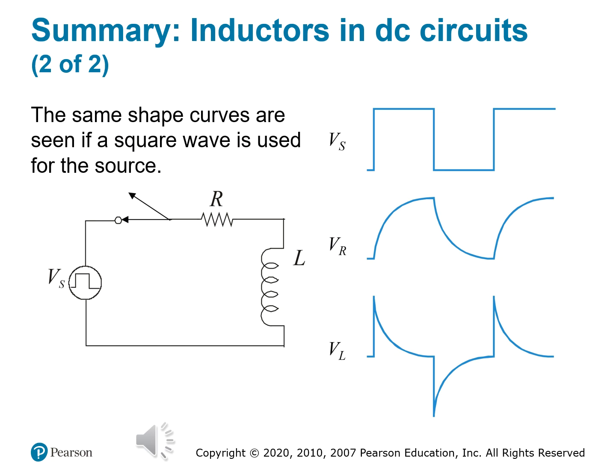If we have a square wave voltage source, V sub S, and that's feeding a series RL circuit, the waveform flips between on and off, basically applying the step voltage over and over and over. This rapid switching is common in pulse width modulation, switch mode power supplies, and digital control systems. And what is the inductor doing? Let's take a look at that voltage in the graphs. V sub R, across the resistor, follows a curved exponential rise and fall. And that's because current through the inductor ramps up and down gradually, even though the voltage flips instantly.